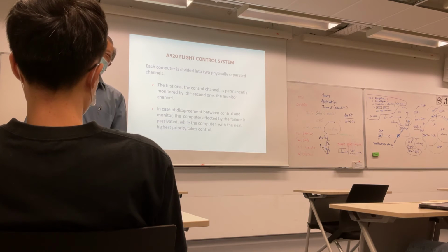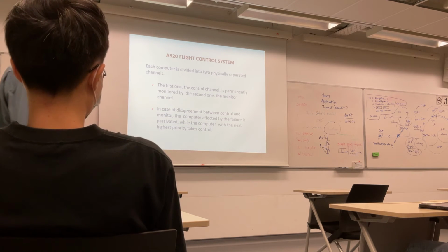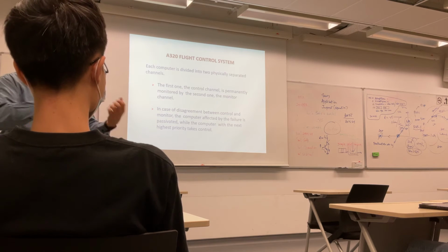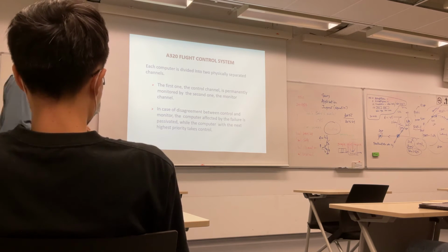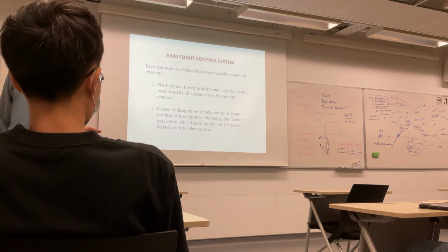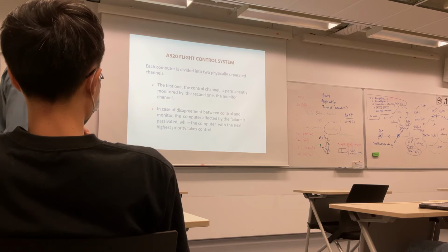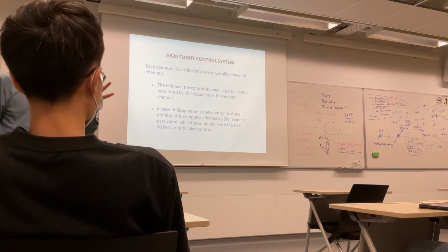I think they learned from there. Yeah, right, you can learn from that. So that's what I mean by fail passive. If you fail, it must not interfere with the other operations. It must not interfere. Now, of course, in autopilot, next week I'll talk to you, you need to have full operation and then fail tolerance system. Today, a lot of aircraft are built with fail tolerant.